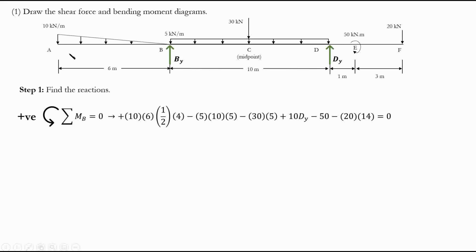So in this case, what would be the lever arm? So this is the load, right? A third from the edge, what does it mean? It's 6 meters. What is a third of 6? It's 2 meters. So it means that from the edge to the centroid, it's 2 meters. So what is the lever arm? 6 minus 2, or 4. So this is the lever arm we're looking for. Basically this was the force, and this is the lever arm. So the magnitude of the force is multiplied by 4, which is the lever arm.